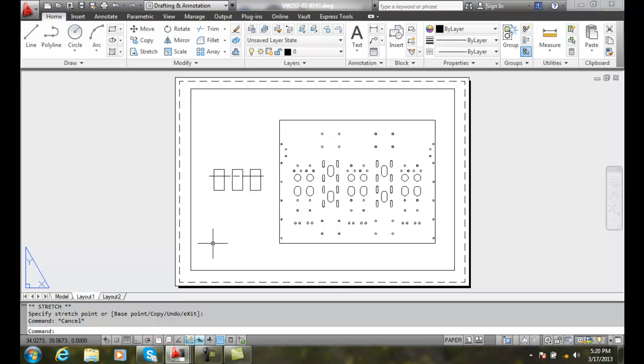I can click inside my model space and activate the model space. And when I click in the paper space, I'm on top of the paper, working on the paper. The size of paper by default is going to be an 8.5 by 11 sheet of paper in the landscape or horizontal orientation.